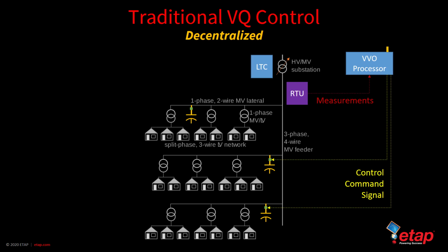The rule-based approach does not work well on distribution feeders that are heavily meshed because the rules become too complex if a large number of switching possibilities exist. Because, again, a power flow analysis is used to determine the rules, it is often not possible to anticipate all the possible operating conditions of DERs in a fixed set of rules. Therefore, the rules-based approach may not be effective on feeders that, again, have a high penetration of DERs in the network.